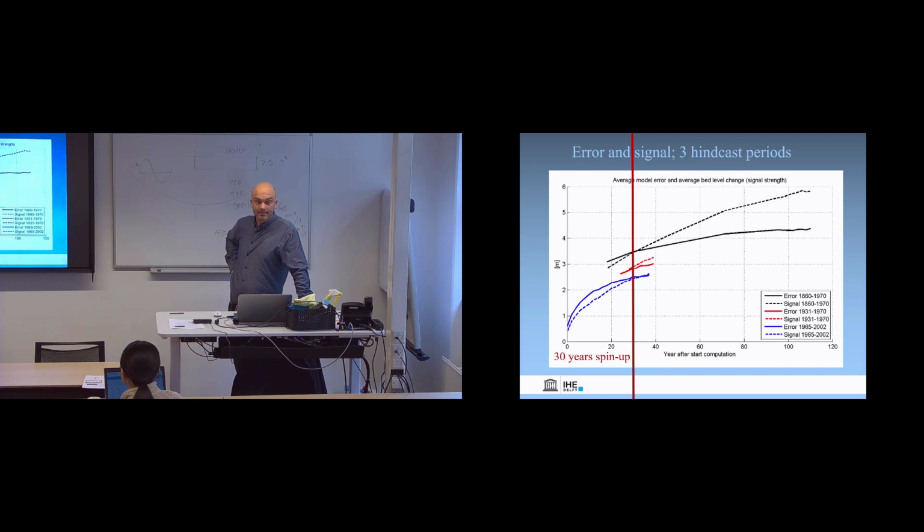Okay, and if I increase the morphological factor, will it give better results? Well, it gives the results faster. If it's better, you have to do by trial and error. But typically, what I see is that morphological factors up to 200, they're safe to go.